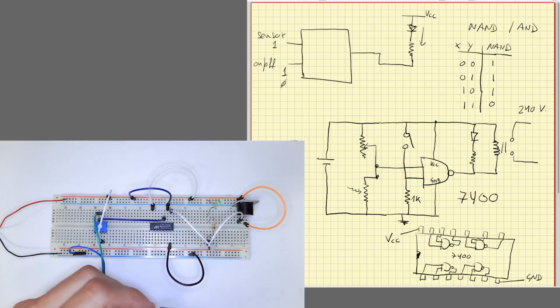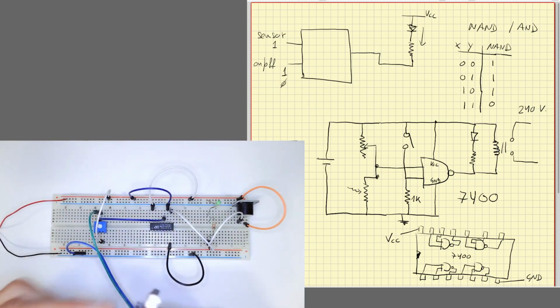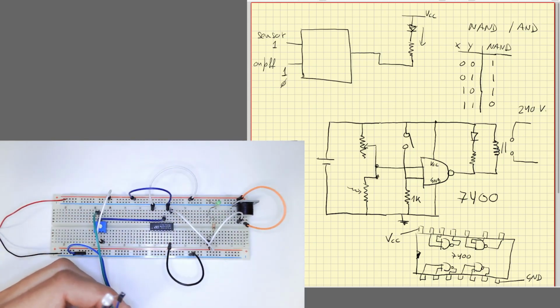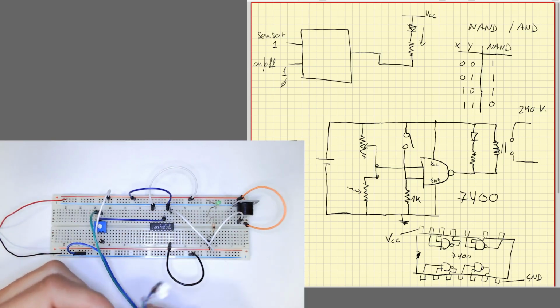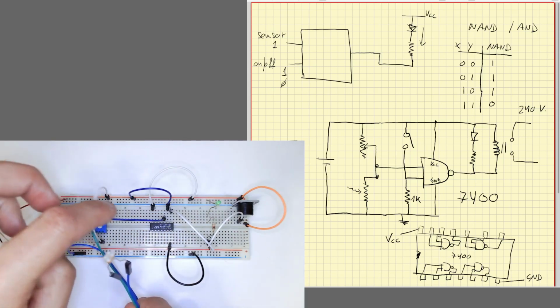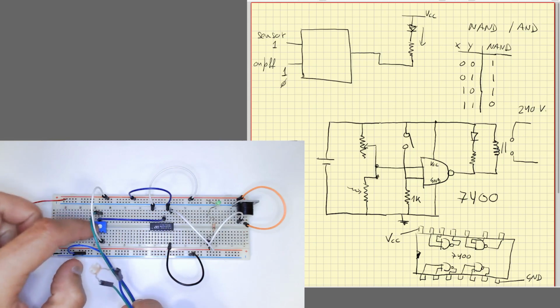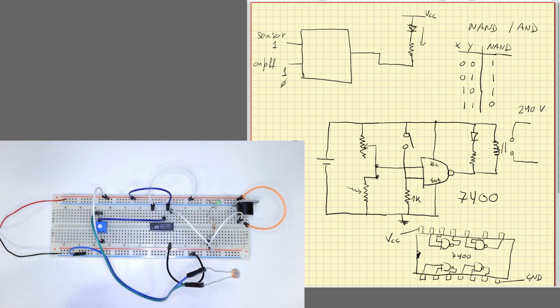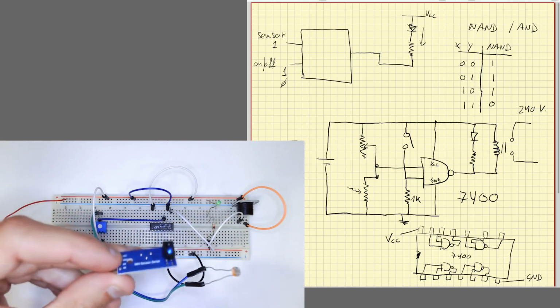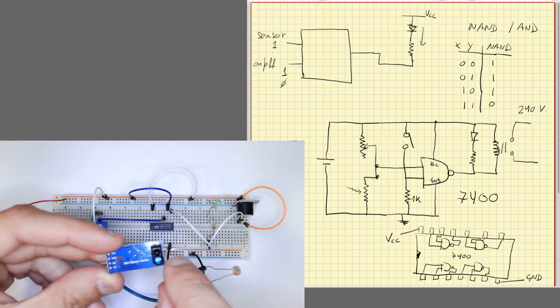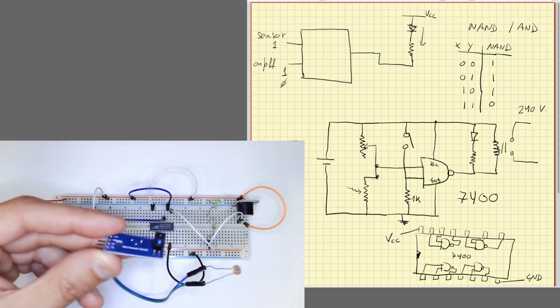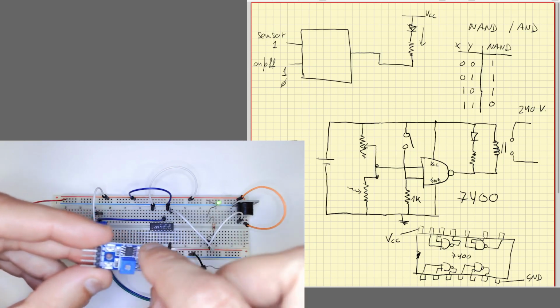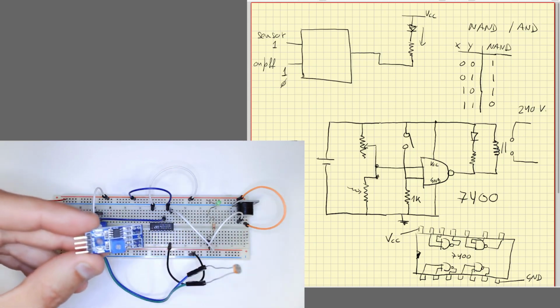Now we have used a photodiode here. We have built our sensor. We have used a device for our sensor. We have used, as we did before, the potentiometer, but there are many types of sensors that are already built. This, for example, is a proximity sensor. It's an infrared proximity sensor that already has the electronics, the calibration potentiometer.